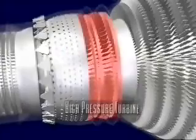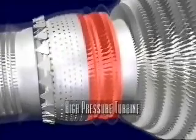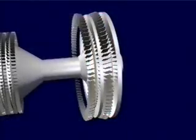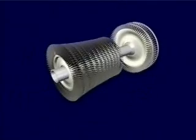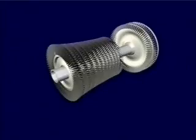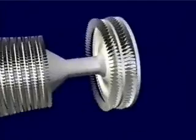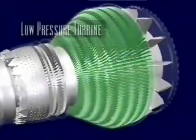Blasting through the high-pressure turbine, the high-energy air spins the blades at over 10,000 revolutions per minute. These blades are connected to a shaft that runs through the center of the engine and drives the high-pressure compressor. In fact, the only purpose of the high-pressure turbine is to extract enough energy from the air to turn the high-pressure compressor. Together, these components make up the high spool. Next, the air passes through the larger low-pressure turbine.